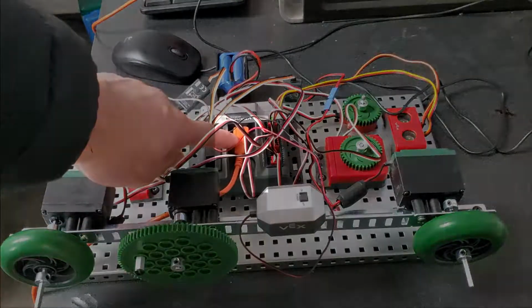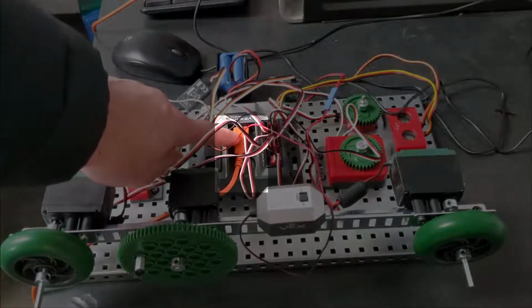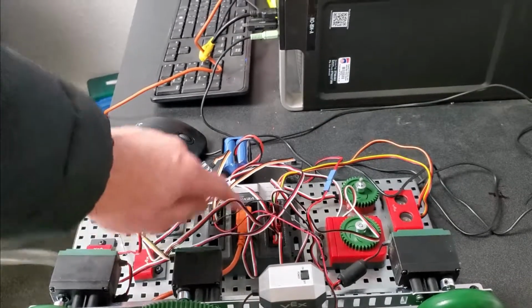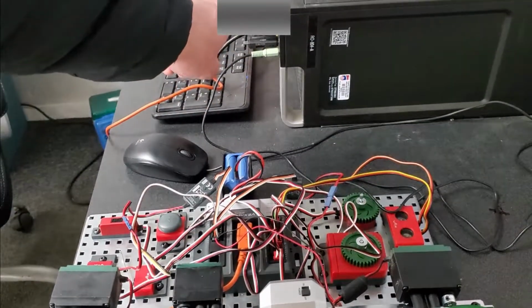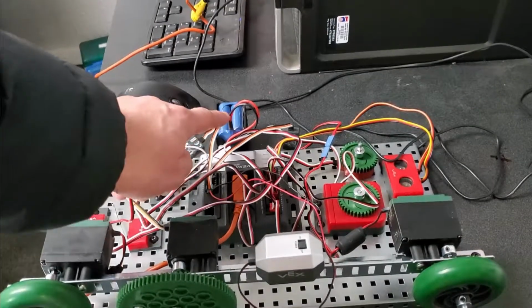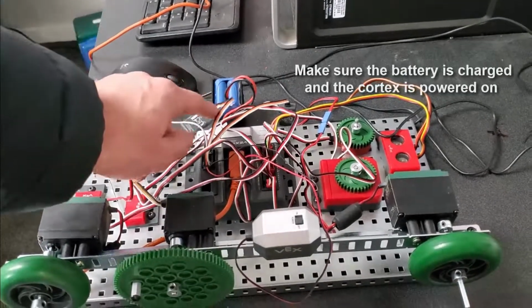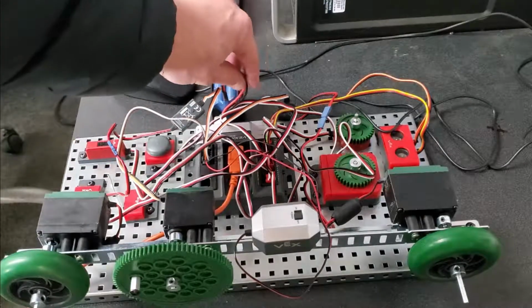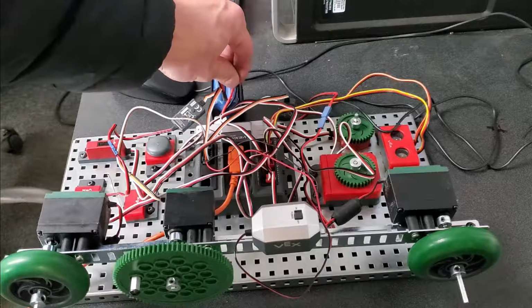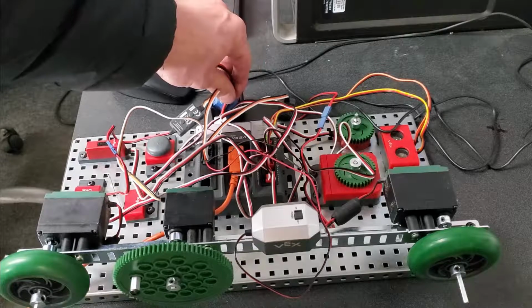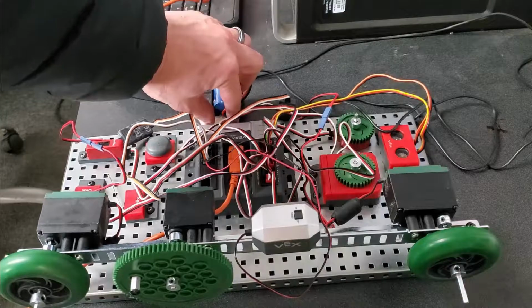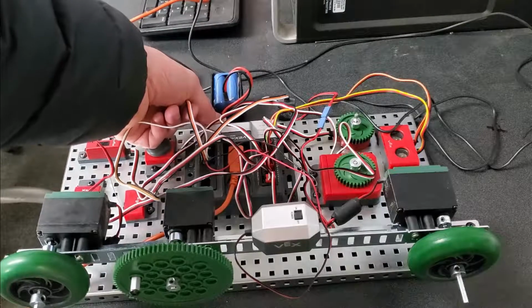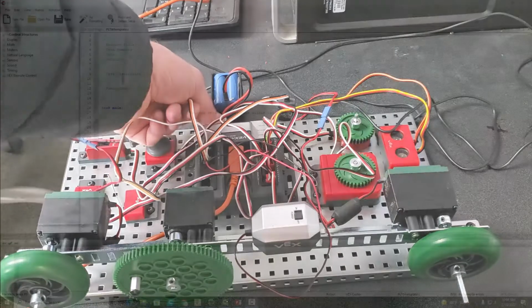All right, so once you have your test bed made, the next thing you want to do is grab an orange USB cable, plug it into the VEX Cortex here, and then run it over to your computer USB port and plug it in. And once that's done, grab a VEX battery and plug it into your VEX Cortex. Please note, never remove your battery by pulling on or yanking on the wires here. You'll mess up the terminals. Always, and I mean always, remove your battery by grabbing this white receptacle, the plastic piece, and pulling it out that way. If you need help, let me know.